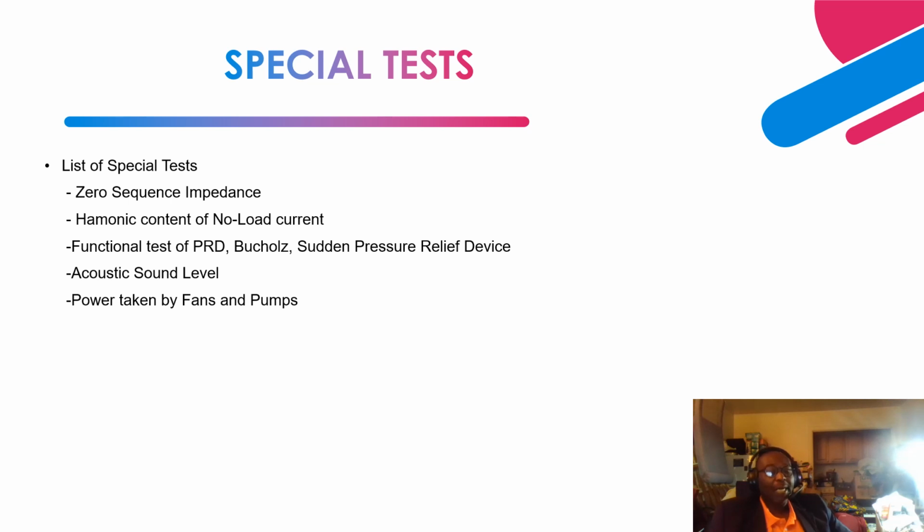So we can utilize that high harmonic content to distinguish between magnetization inrush and an actual fault condition. We utilize the second and fourth harmonic that are measured to accurately set this relay, to prevent spurious, inadvertent trip of the differential protection during energization of the transformer.